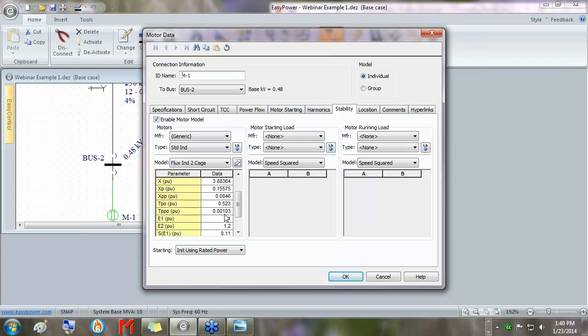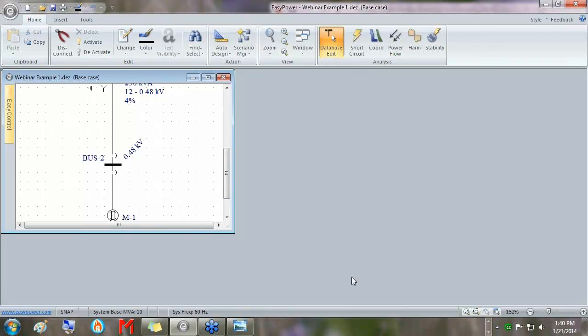And you'll find that this may cause your simulation to go numerical. I mean, we recover from it nicely in this dynamic stability package. We'll just tell you, hey, you have numerical issues, you need to lower your time step. And so all you do is go in, options, lower your time step. It'll take the simulation a little longer to run, but you have to cover for this condition. When you're starting motors, that's one thing you have to understand about any type of transient motor starting dynamic stability: you have to have a very short time step because the frequencies in the rotor are 60 hertz under starting conditions.